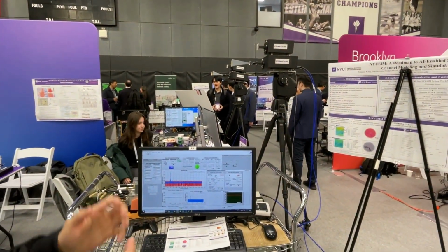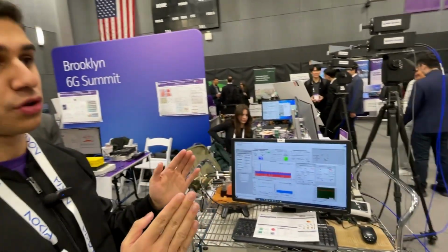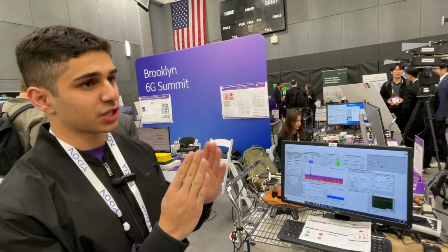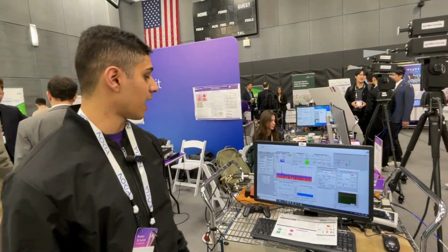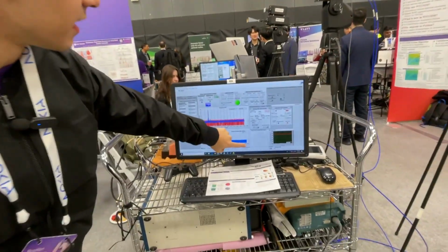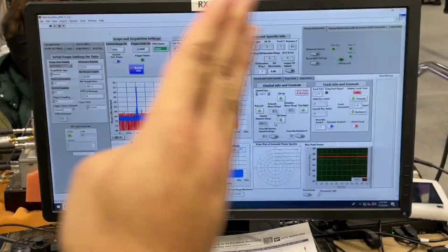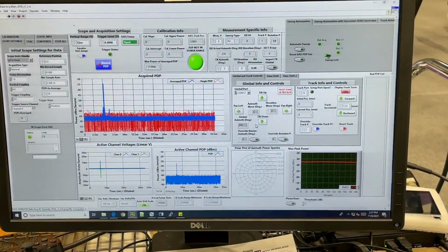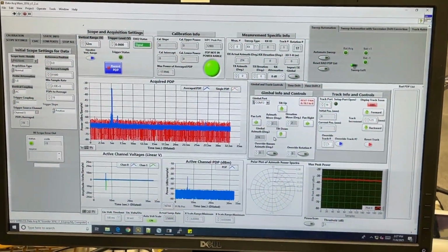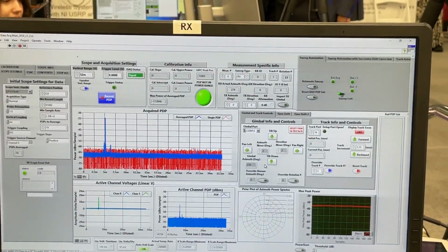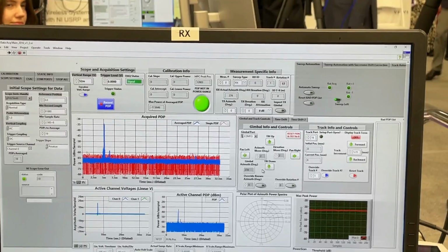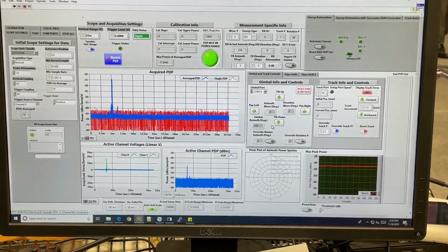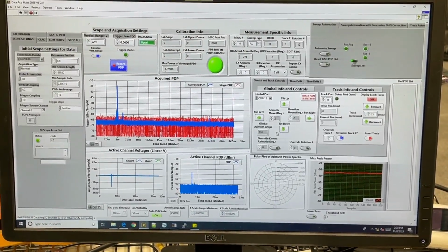And at the receiver end, we generate that same signal using the same pseudo-random noise sequence at a slightly slower clock speed. And what that allows us to do is get a time-dilated power delay profile, meaning it gets slightly stretched, and that allows us to get a much clearer view of the channel. And all this essentially contributes to opening up new bandwidth, as things that have not been seen before are now able to be seen, and with the gold standard of data.